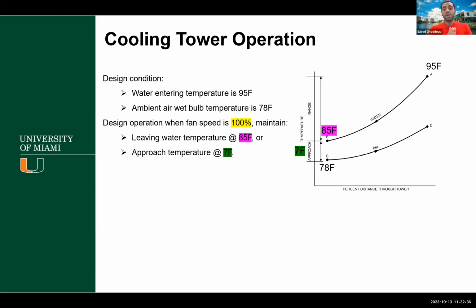For the design condition in designing a cooling tower, we need to consider the water entering temperature as a standard of 95, and also the ambient air wet bulb temperature of 78.